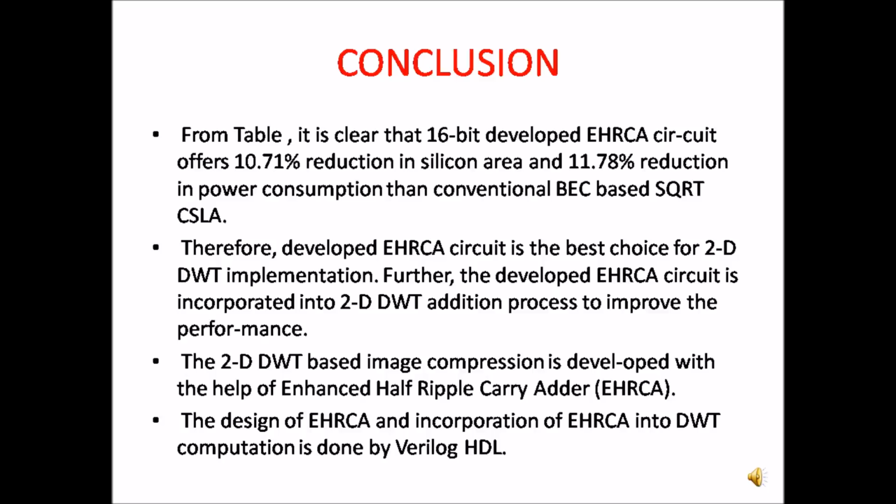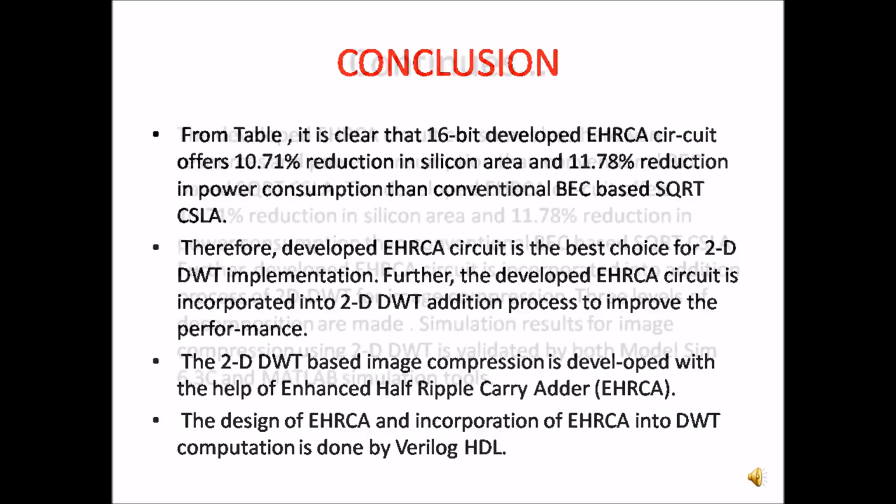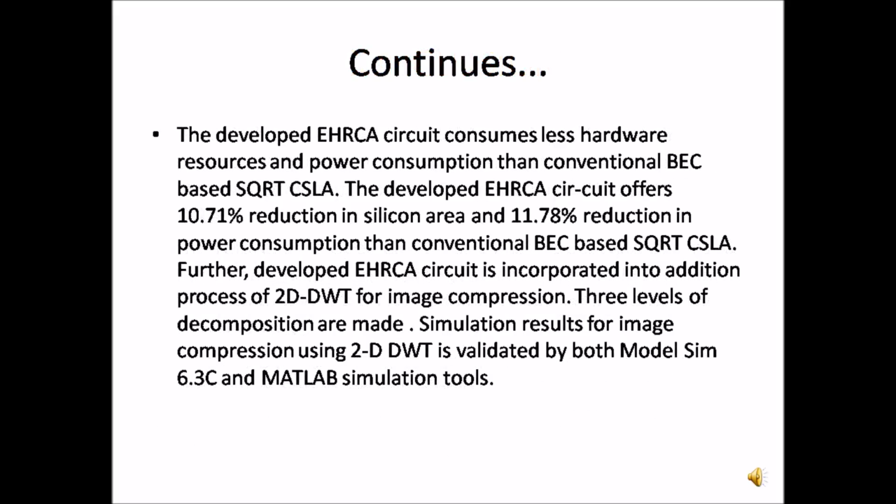From the table it is clear that the EHRCA circuit offers 10.71% reduction in silicon area and 11.78% reduction in total power consumption than the conventional BEC based SQRT CSLA circuit. The developed circuit consumes fewer hardware resources and less power than the conventional BEC based SQRT CSLA. The reduction in power and silicon area consumption than the conventional BEC SQRT CSLA circuit is more.